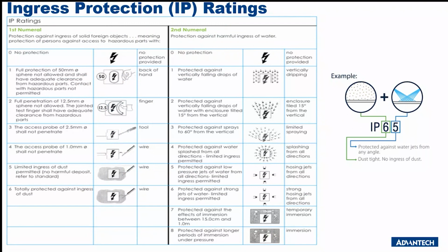Okay, next one is when we're discussing the IP, IP65 or IP66, I just want to elaborate on this one. IP means ingress protection. The first number digit is about solids, we can see here on the left side. Then the second digit is liquid.